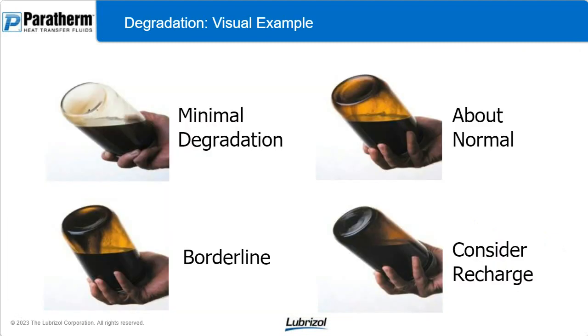Check your fluid visually when you take that sample. If you see anything with a lot of solids or chunks or very, very sooty, the viscosity is going up, the color is really dark, those are red flags. Still send it to the lab to get checked, but you should just have an idea that that fluid might need to be acted on.